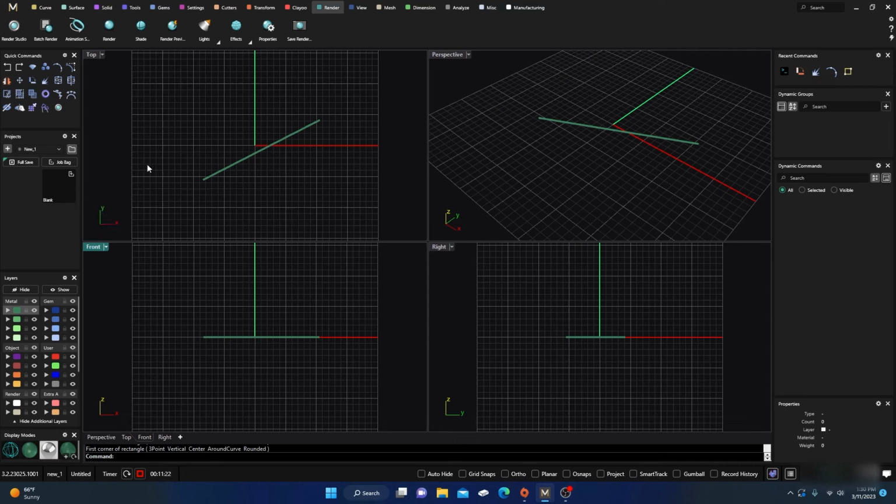But the job bags can come in very handy to be able to save things as you're going along as well. Next one here is layers, changing layers. You can change it to any layer you want by clicking on the arrow. If you select it and then click on it, it'll change to whatever layer you want. And you can actually hide those layers, or you can lock those layers. So now I cannot even select it at all because it's locked. Those options are very good at certain times, so you'll need to definitely be aware of them.